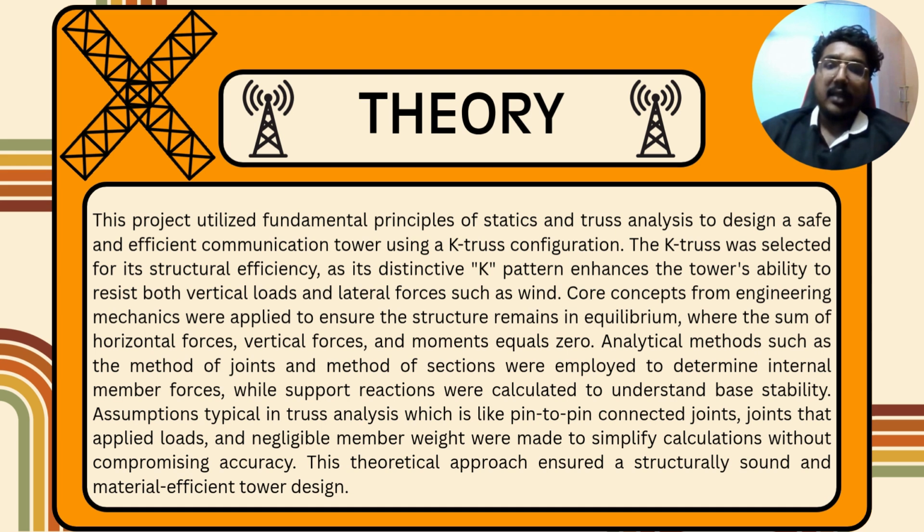Assumptions typical in truss analysis, such as pin-connected joints, loads applied at joints, and negligible member weight, were made to simplify calculation without compromising accuracy. This theoretical approach ensures a structurally sound and material-efficient tower design.